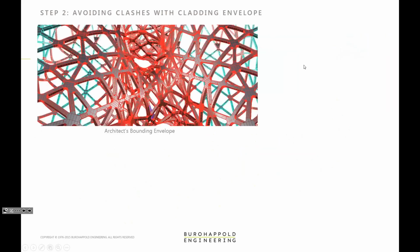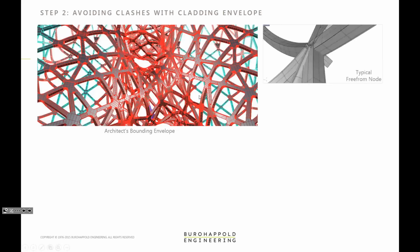The other thing we had to do was the architect had an envelope for the building, which was the cladding. They had a thickness for the cladding. We had some tolerances. We had some fire protection. And then we get down to the base structure. We had to devise these connections such that they didn't poke out. If they poked out with this complex bounding envelope, it would mean that the cladding would not fit. So we had to prove that that wouldn't happen.